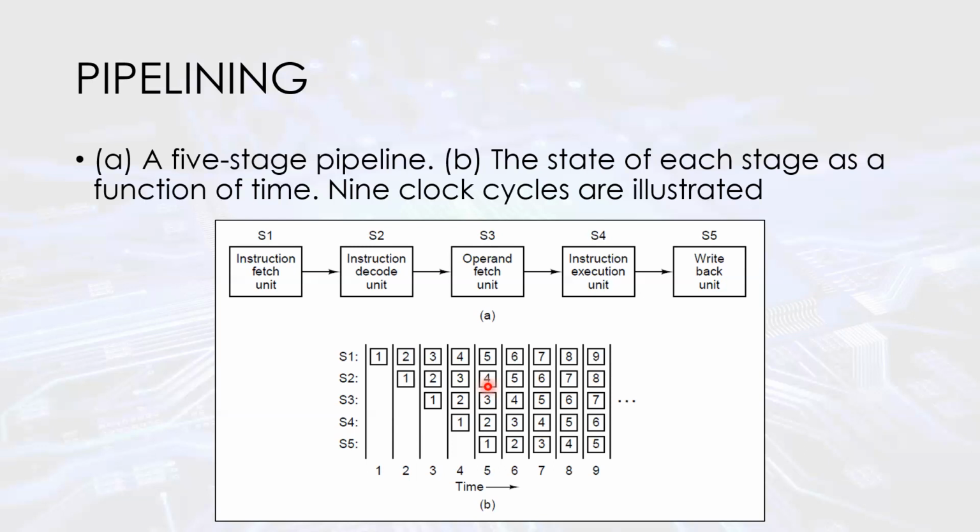So same thing here. This is really generic, but it's pretty typical where we would start pipelining with these five stations, where each station is just doing this one task. Once they fetch the operands here, they pass it on, and so on and so forth. Okay, and the idea is that we're really going for throughput here.